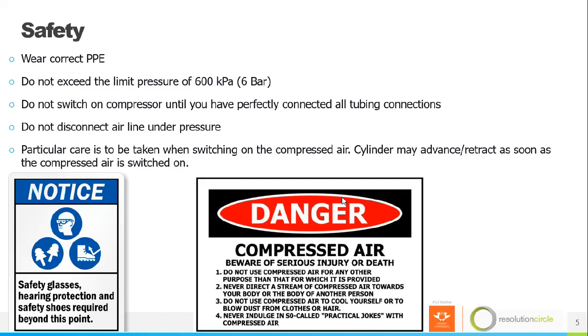Particular care is to be taken when switching on compressed air. Cylinders may advance or retract as soon as the compressed air is switched on. So before you switch on, make it a point that you clear all spaces or you move away from the cylinders, because the piston rod of a cylinder may advance any time if you apply pressure on your system, which might cause harm if you are not cautious.